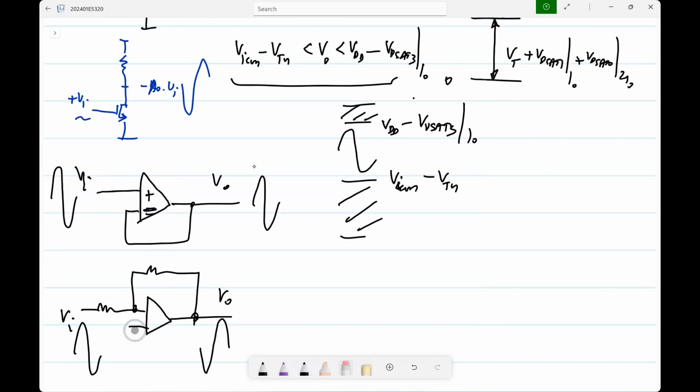Whereas in this case, because the common mode is not moving, you can set the common mode to be in some range that is permissible, and after that you can let the signal be limited only by the output swing limit. That is one of the reasons why this is a lot more user friendly than the other one. It has its disadvantages, but it's what is more commonly used also. So this is how you use it. You have a swing limit on both the common mode and the output signals. One way is, assuming ideal op amps, you calculate the outputs, you calculate the common mode, and then you can put restrictions based on the common mode swing limit and the output swing limit. Of course, whichever is the worst case will be the limit.